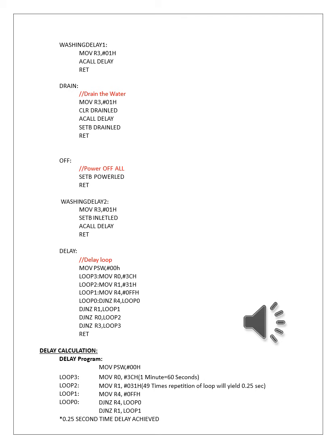Mainly the logic in this program is that we create the time delay for each and every operation, and we set the port and clear the port, so the LED will turn on and the LED will turn off. SETB and CLR are bit handling instructions, and they are very powerful instructions mainly for on and off. If I take a microprocessor and want to interface any peripheral devices, I need to initialize the 8255 mode first, and only then can we connect. But the microcontroller has many advantages. We can easily communicate with the peripheral devices, and using bit handling instructions we can set the bit as well as clear the bit. So we can do the on and off using easy coding.